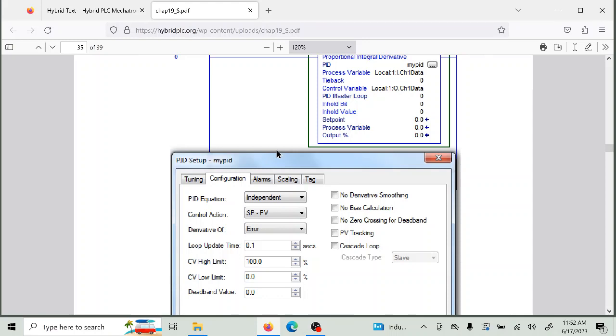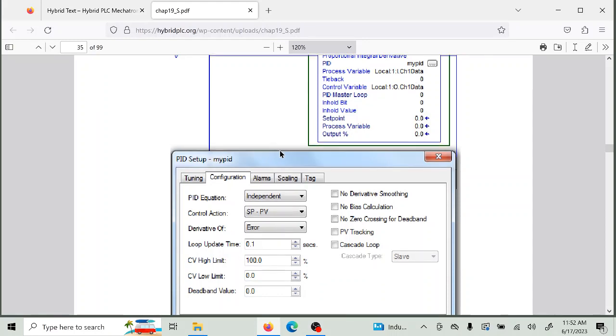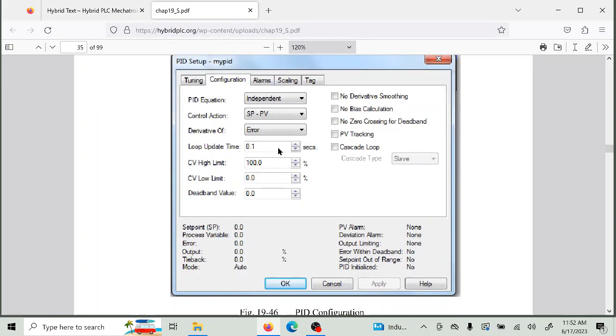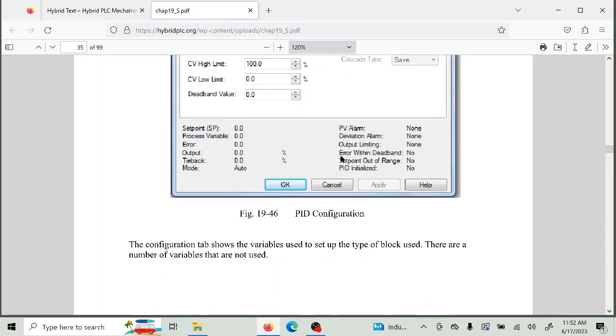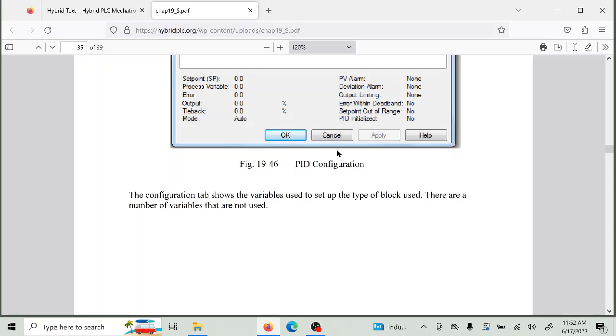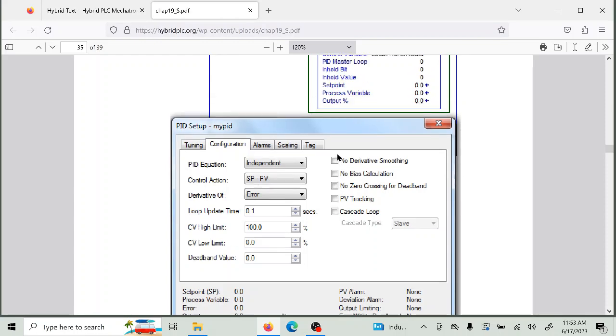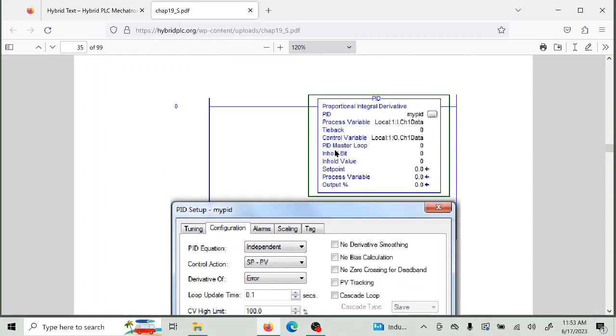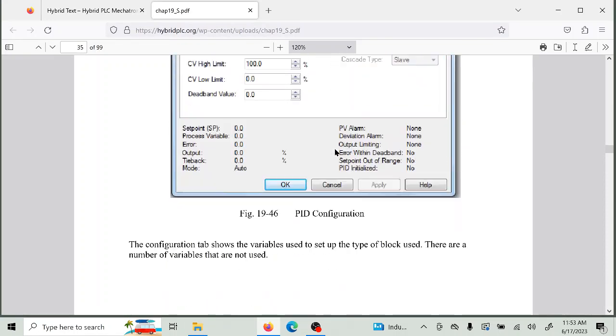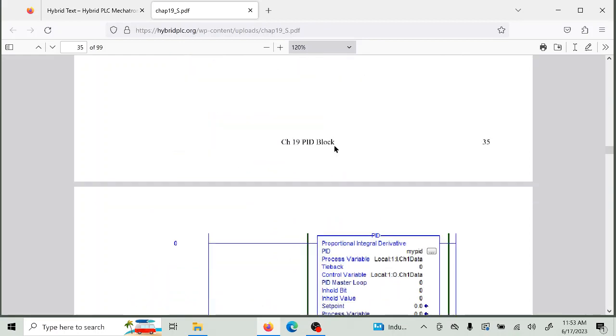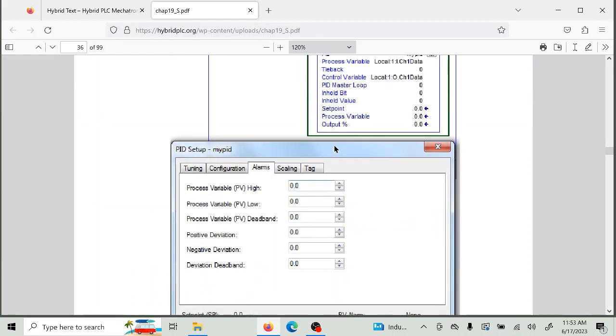Or you have to go through an automated tuning process, or you have to use some other process to look at it. But again, I cannot say it too much: usually using common sense and knowing kind of where the tuning parameters are, you'll get it, and you'll get it very quickly. You'll see that it's either too sluggish or it's unstable or it's okay.